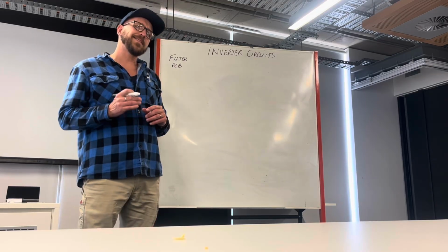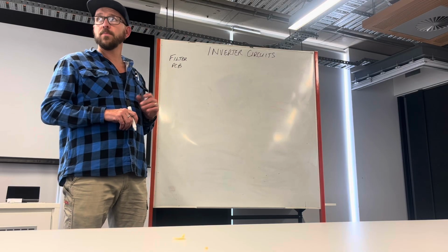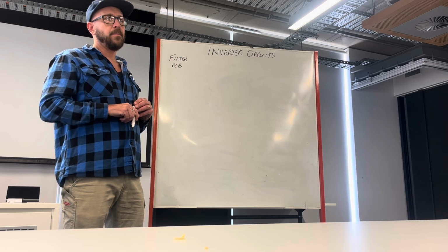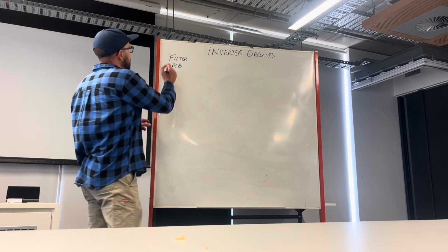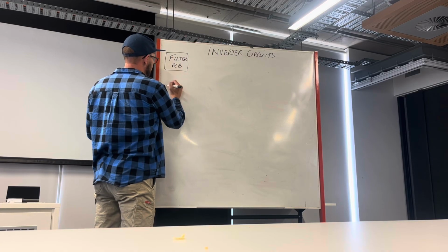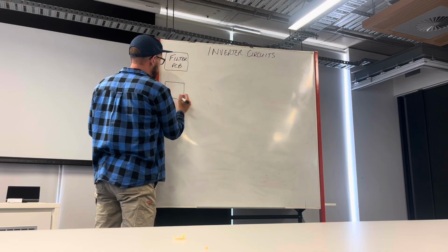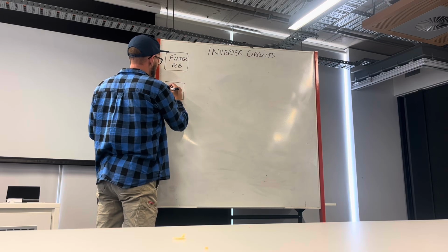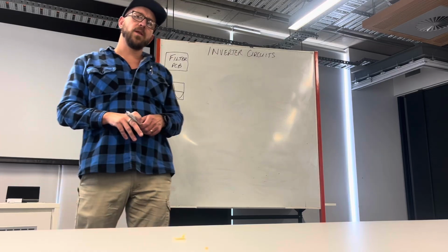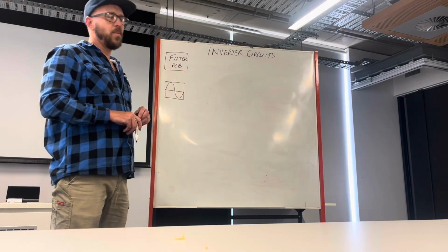It usually also has a current transformer on it that monitors the current draw of the whole system and gives a signal to our control board, letting it know what the current draw is. So that's our filter board there, and I'm going to draw underneath each of these what we've got going on with our sine wave. So to start with, we've got AC voltage, alternating current, normal AC sine wave, single phase.